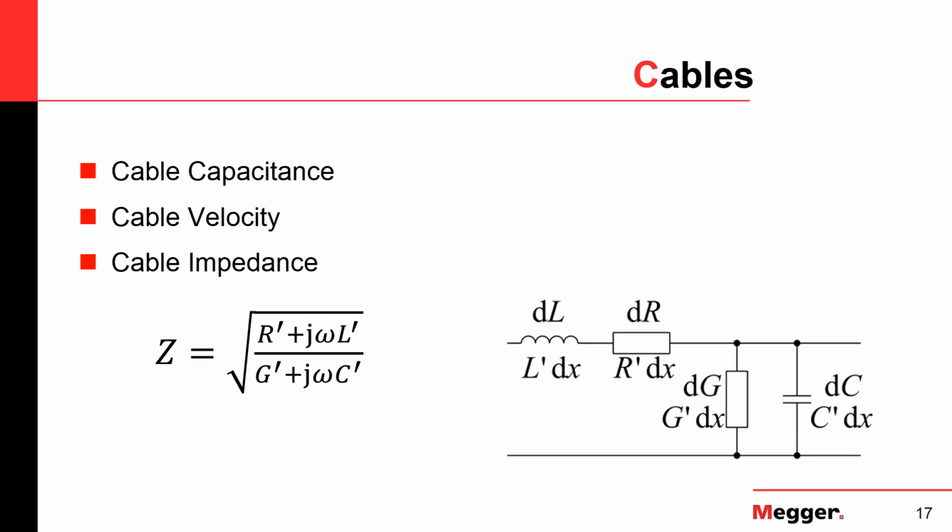And then we have the impedance. Now, don't be scared by the math in case you're not a math guy. This is pretty much important later for some of the pre-location methods. The impedance is determined by two things mainly. There's a material influence, which is the resistance.